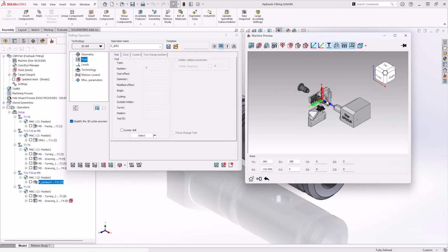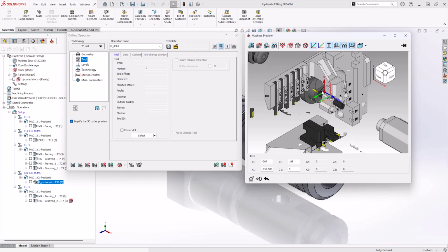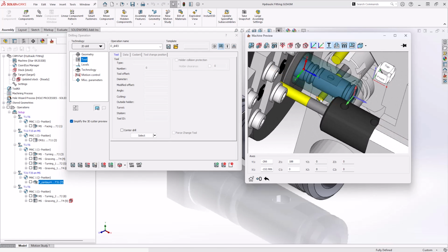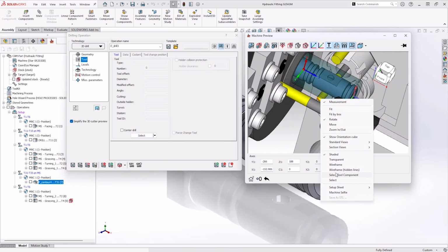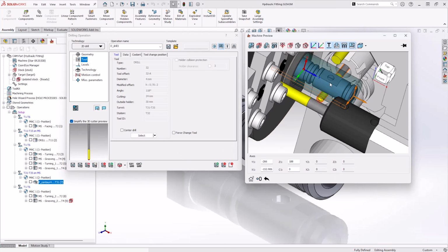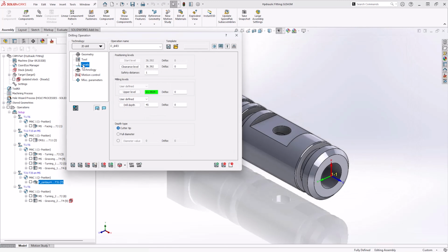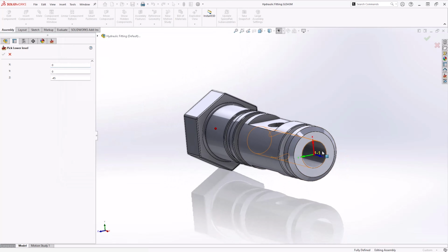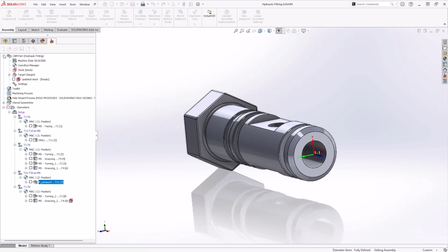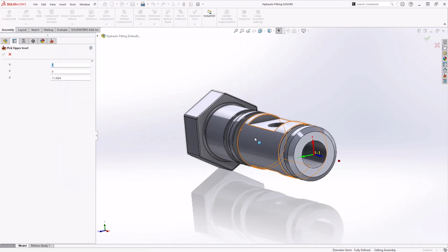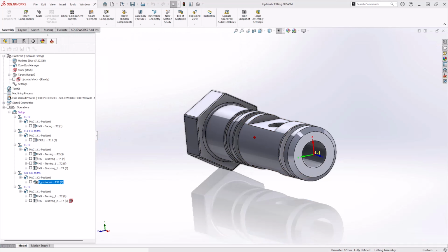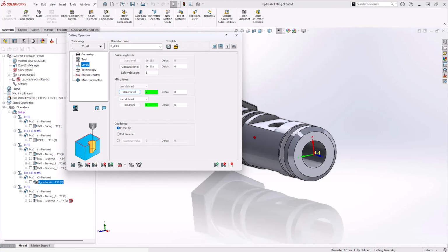Say for sliding head machines, the machine preview is an excellent option for this. We can find exactly what we wanted to do, and then go and find the upper and the lower level of the drill. At the same time, we could have also gone and changed the technology depending on how we want to drill. Maybe potentially want to peck it this time. You can see as well I highlighted the drill depth by the bore. We can do this because we're working around that 4th axis, remember.